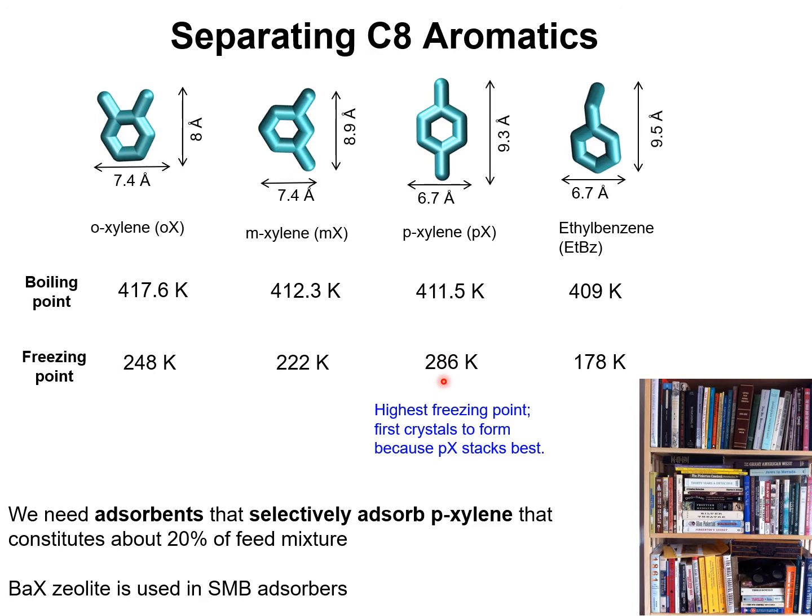And when the solution of C8 aromatics is cooled, the first crystals to come out of solution consist of para-xylene. This is because para-xylene stacks most efficiently to form crystals. Fractional crystallization is also a commercially viable technology for separating C8 aromatics.